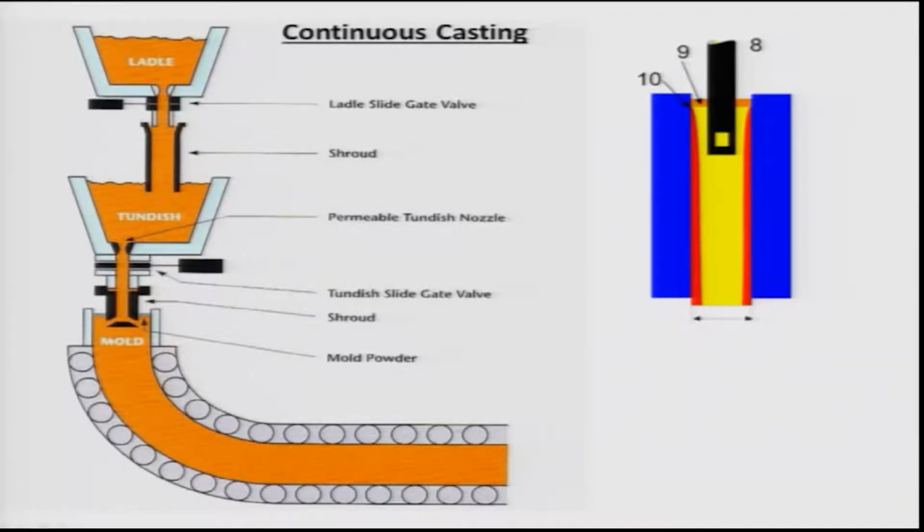As the basic picture shows here, as the liquid metal is poured into the water cooled copper mold, a thin layer, or skin, solidifies at the interface, and inside it still remains in hot liquid condition. So again the nucleation happens at the interface between this solid copper mold and the liquid, and this is again heterogeneous type nucleation.